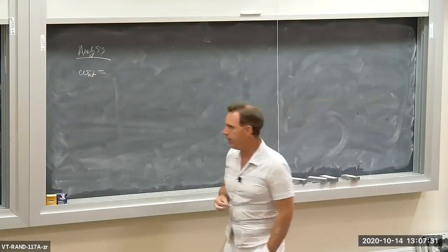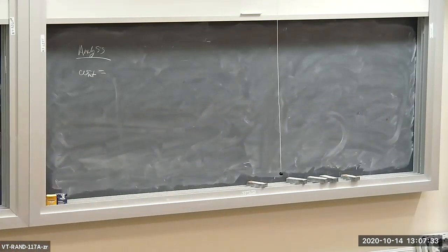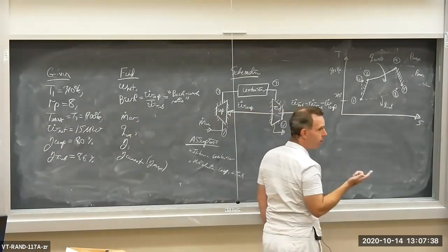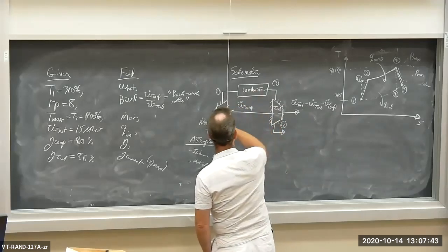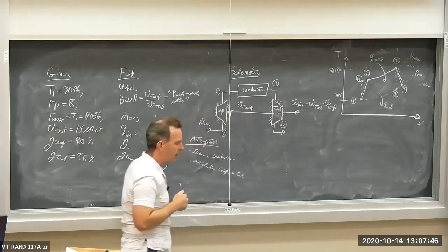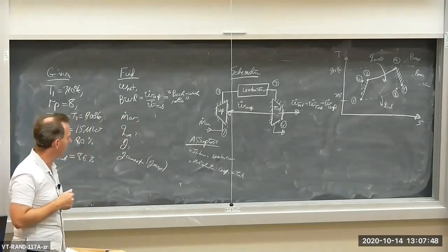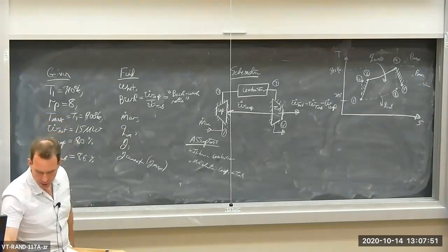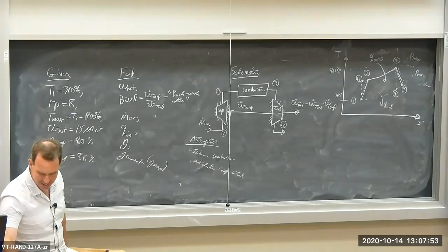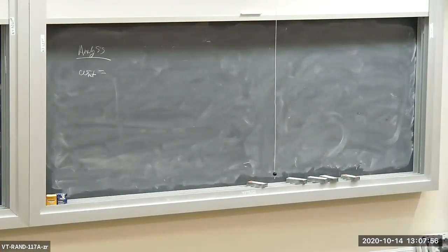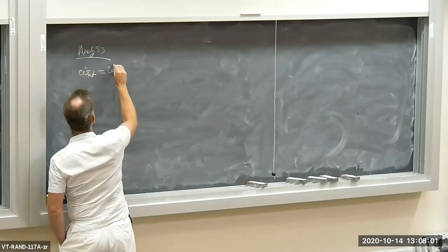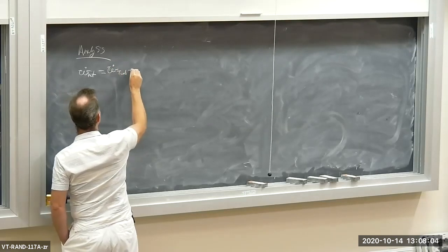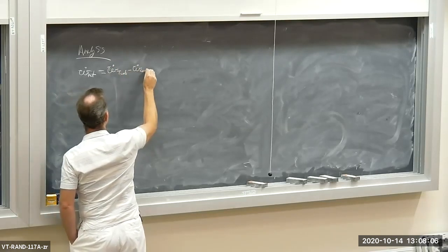Now, w net is the difference between the turbine and compressor power, or work per unit mass. So assuming the m dot is all the same throughout the cycle, then the difference between the compressor and turbine power is the net. Okay? So let me write here, W dot net is equal to W dot turbine minus W dot compressor.